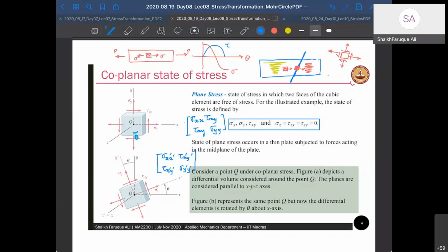That's why we do stress transformation. Given another plane, let's say this is another plane, and it makes an anti-clockwise angle of theta. We need to find the stresses along the planes which are along that new axis. So if this is your x and y axis, the original axis, and then you have this x dash, which is the new rotated axis, you draw a perpendicular to x dash, another perpendicular plane to y dash.